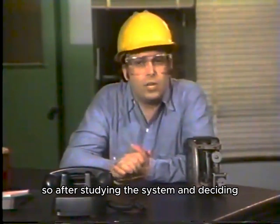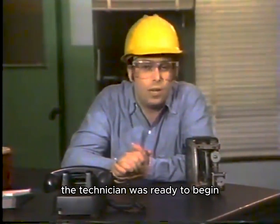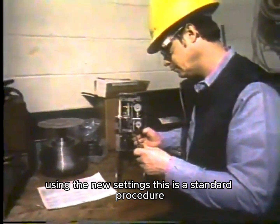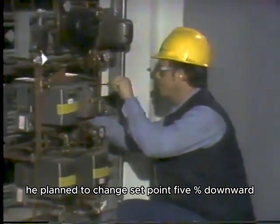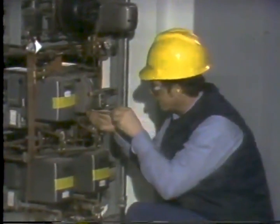So, after studying the system and deciding basically how he was going to tune it, the technician was ready to begin. He decided that he would remove the controller, take it to his shop, and calibrate it using the new settings. This is a standard procedure. After putting the controller back in the system, he planned to change set point 5% downward and see how the system responded. If the system stabilized at the new control point in about 15 minutes with minimum cycling, it would be tuned.